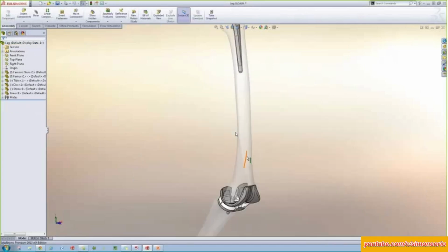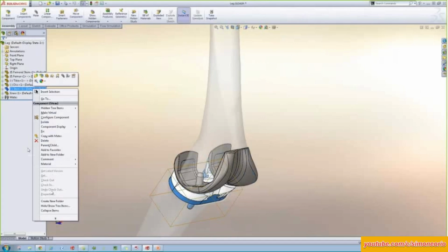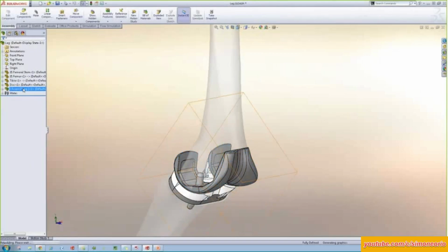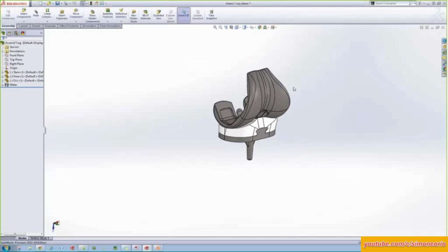Okay. Then from here, we're going to put the knee, the disc, and the stem into their own subassembly. You can see it's just as easy as dragging components and dropping them into their own window. Why would I want to put these components into a subassembly? Because if I open that up in its own window, all of these parts have material associated with them: a density, an elastic modulus, a Poisson's ratio, things where we can get weight and do simulation, so analyze stresses or vibration.